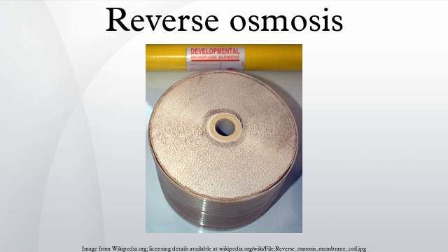For instance, water from Israel's National Water Carrier typically contains dissolved Mg levels of 20 to 25 mg per liter. Water from the Ashkelon plant has no Mg. After farmers used this water, Mg deficiency symptoms appeared in crops, including tomatoes, basil, and flowers, and had to be remedied by fertilization.